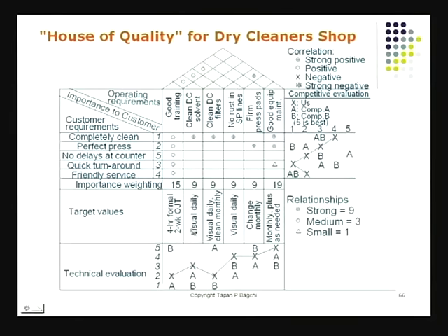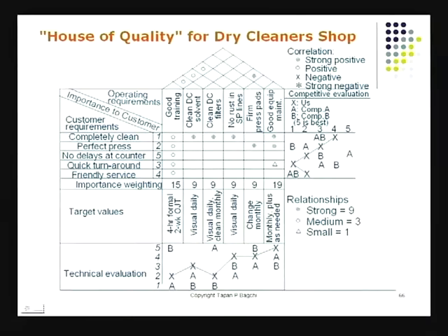The cleaning of the solvent, how should it be checked? Well, you could do visual checking. If you pour it in a test tube and look at the clarity and so on, you should get a pretty decent idea whether this solvent can take another round of dry cleaning or whether I have to change it. That could be done. Again, the filters, how would you check their quality? We could do visual checking every day. No rust, again, a good check is going to be doing the proper rust checking, but we could do it in a shortcut manner, by doing some visual checking.